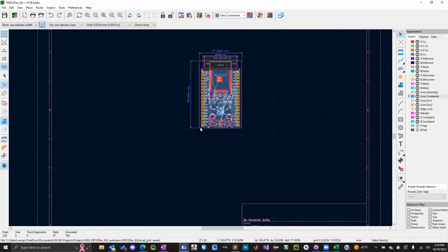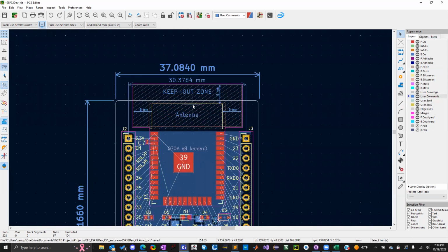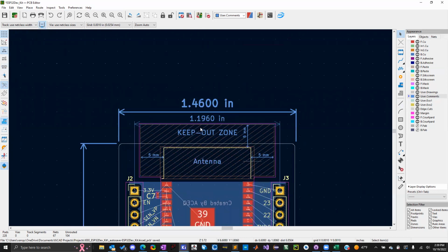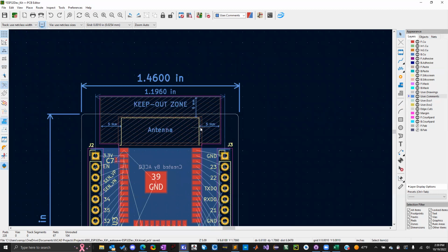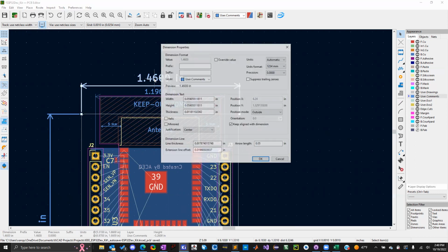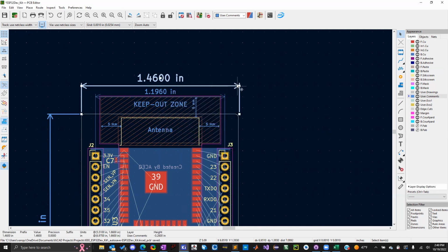0.1 inches, okay. So it's 2.54 millimeters. And then what is the distance between the center of the board where the two sides are, like where you usually put the IC? Is it 0.3? So it has to bridge the gap, that's 0.3. And then 0.5, 0.7, 0.9. So we need more like 1.5, right?